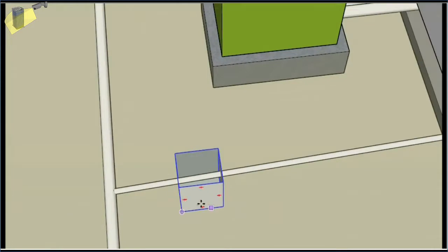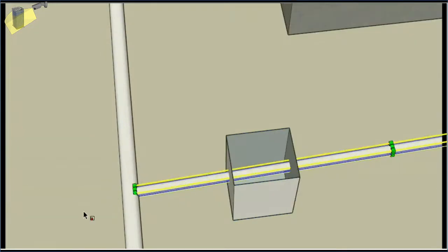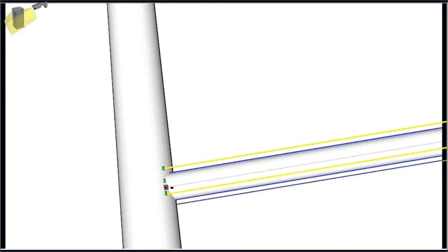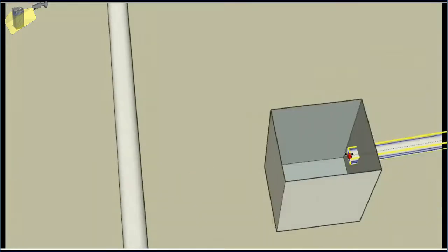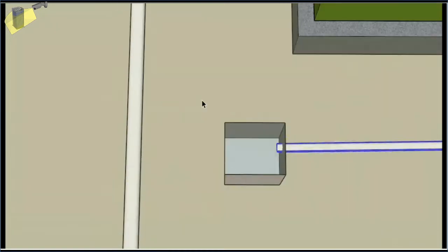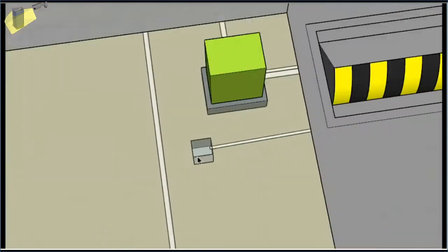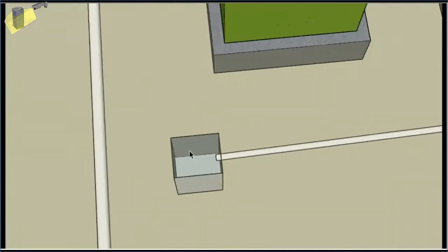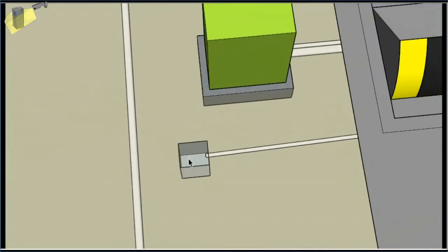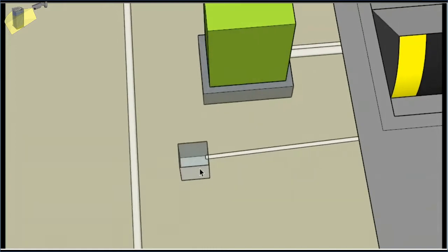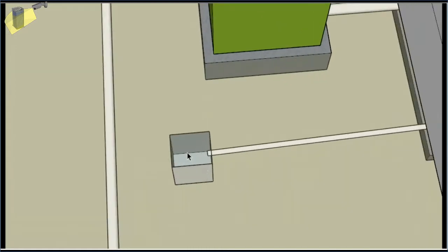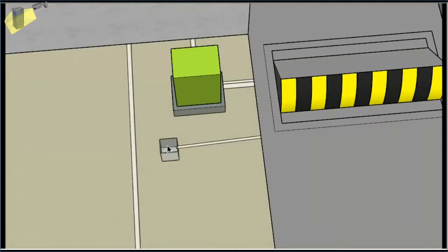So the pipe will reach this pit only, in the case where you don't have a sewage line or a drain pipe near. This pit contains a submersible pump, which runs on a motor. That submersible pump will operate automatically whenever this pit is filled with water. The pump will start working automatically, and it will pump the water outside on the grass or wherever you want it to pump the water.